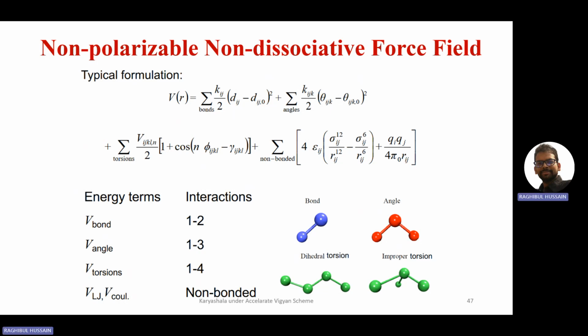So normally when we are doing these organic molecule simulations, we use GAFF or CGenFF or OPLS, which is applicable for any kind of organic system. But for biomolecule systems, particular force fields are useful. You cannot randomly change from one force field to another. You will get drastically different results. Now this is clear, right?